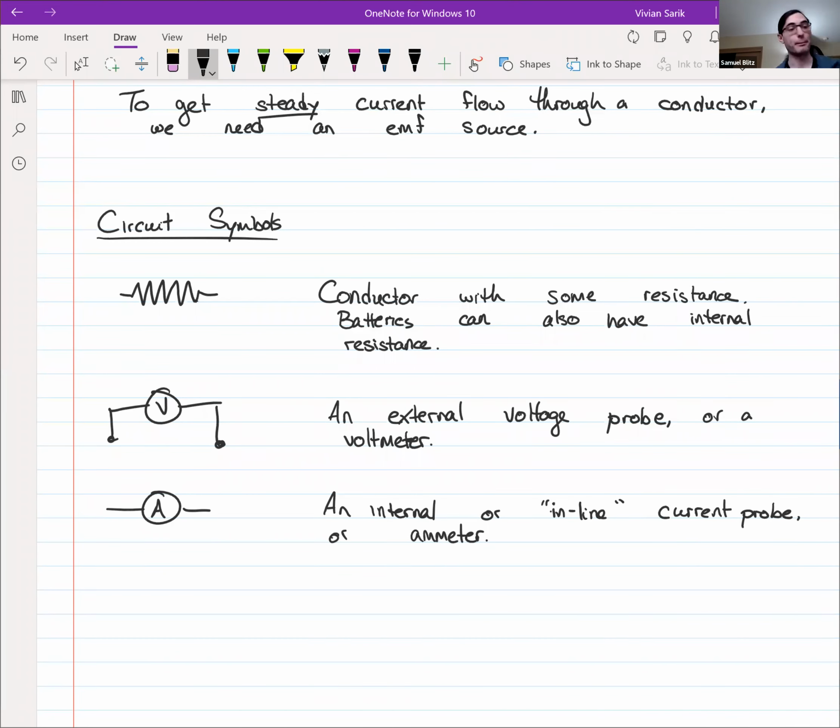You dropped the P. So to measure current using an ammeter, it's not enough to just stick these wherever you want and measure the current between those 2 points. If you want to measure the current through a place or through a region, you have to stick the ammeter in between that place where the current is coming from and where the current is going to. So you have to break the circuit and then connect the 2 ends to the 2 ends of your ammeter.